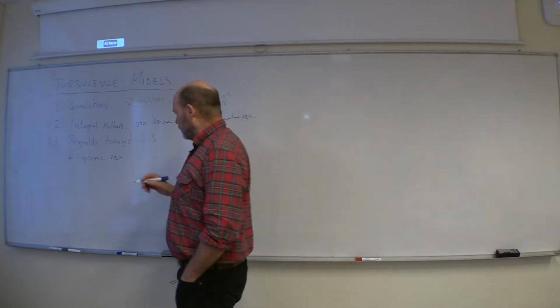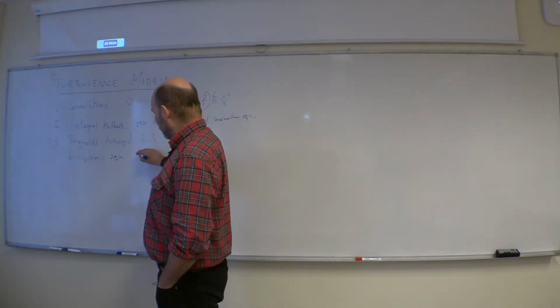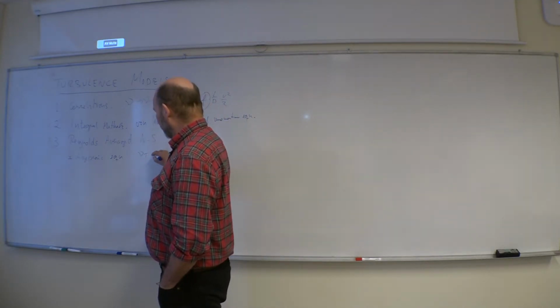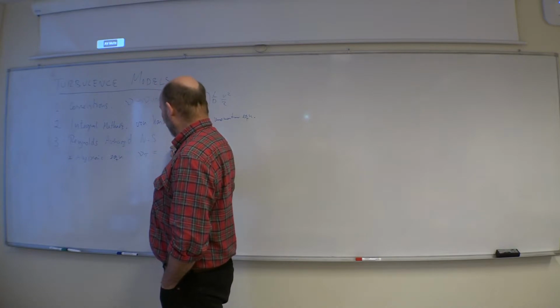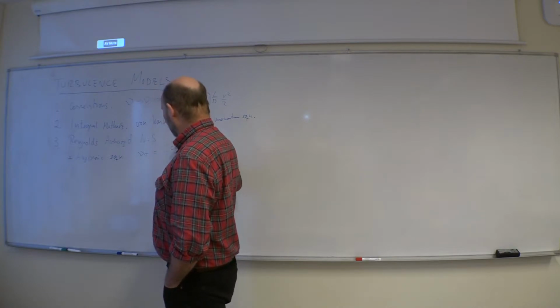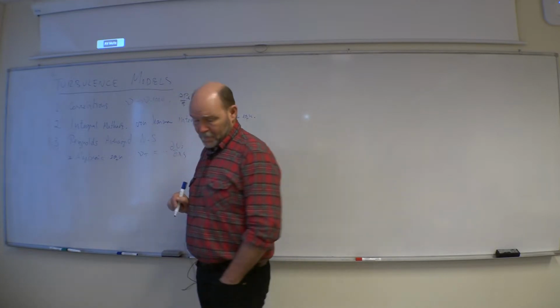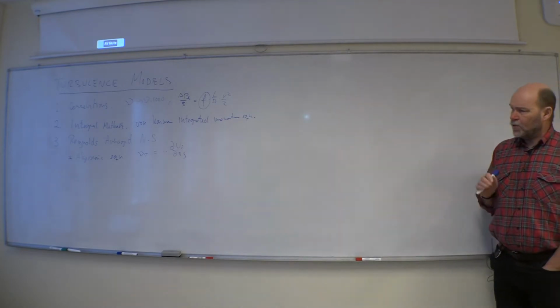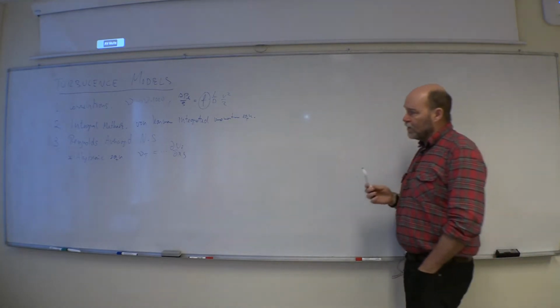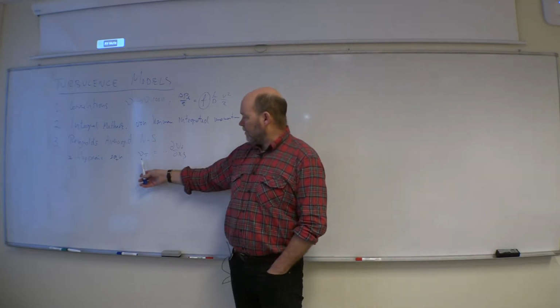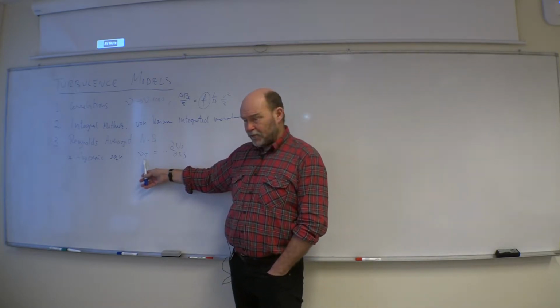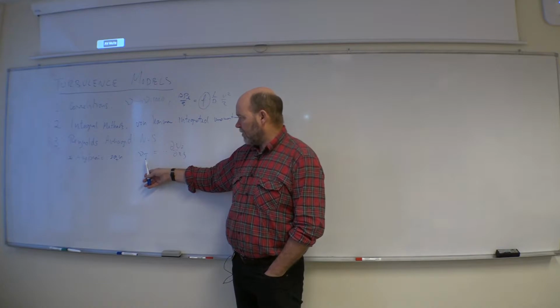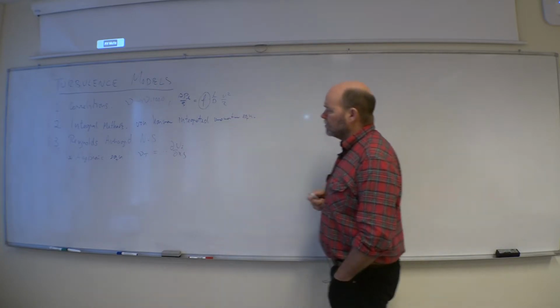Some Prandtl's mixing layers. You will have an eddy viscosity given by something, a gradient of your velocity inside your simulation, stuff like that. So you just sort of increase the viscosity. You add an eddy viscosity, for instance. That's quite typical for these algebraic equations.